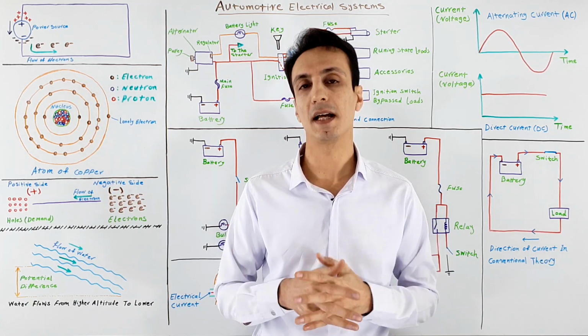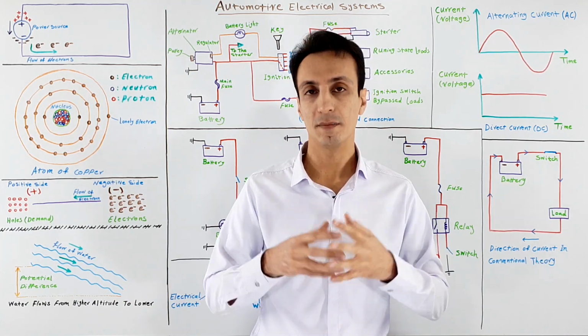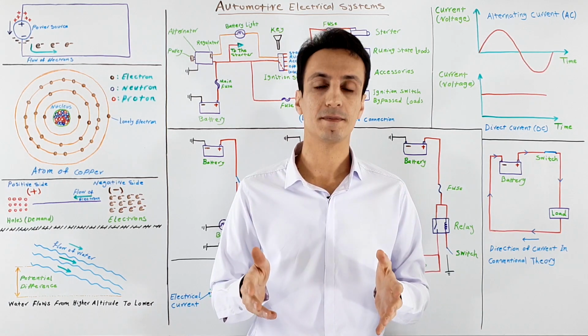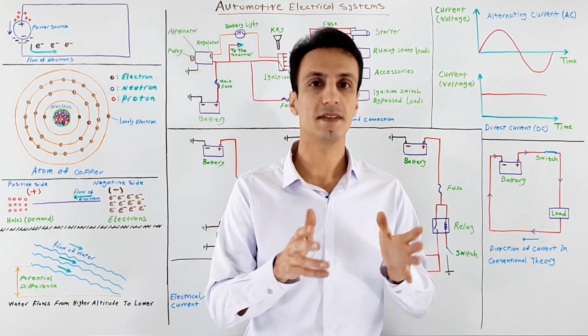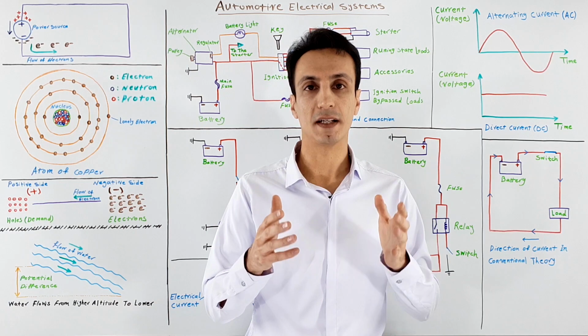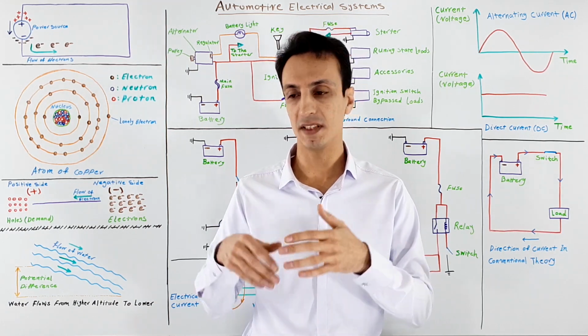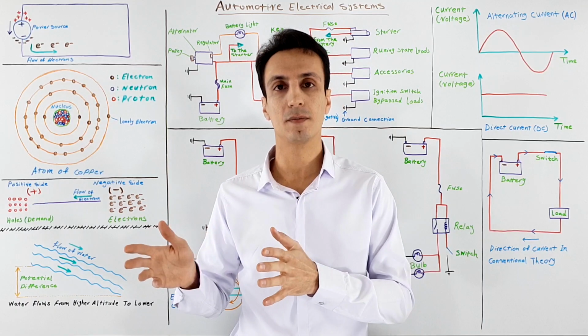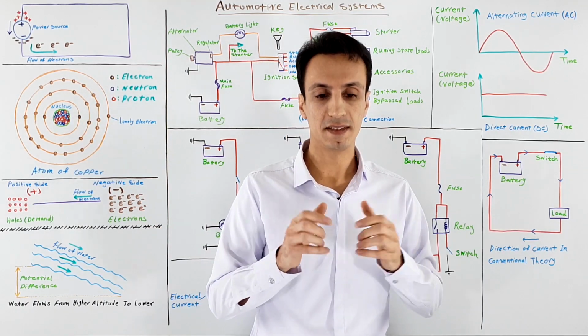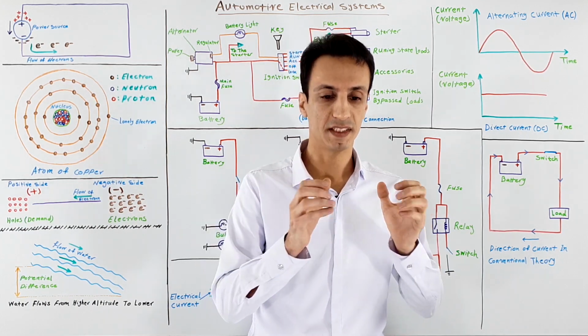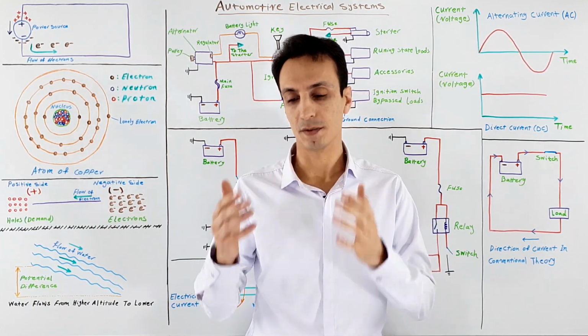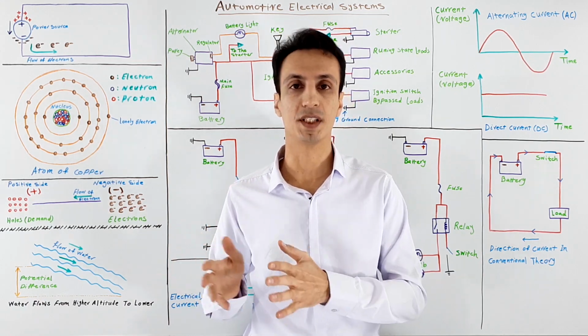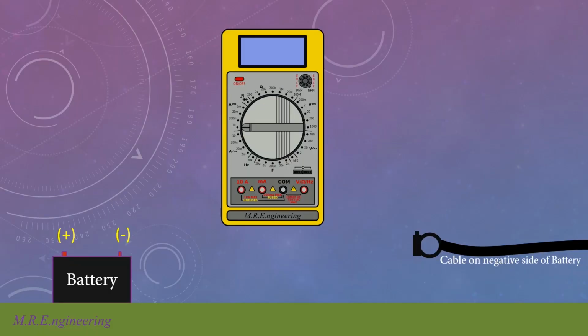When the car is off and even the key is out of the car, the battery voltage is present and can be used. Some systems and components use this electrical power when the car is off and is in parking state. One of these systems is the security system that is vigilant for any intrusion, and also the engine control module, like many other modules, is receiving constant battery voltage to retain some data in memory and also perform some leakage tests and calibrations even when the car is off. Normally, a typical car consumes about 20 to 50 milliamps of current during parking time.